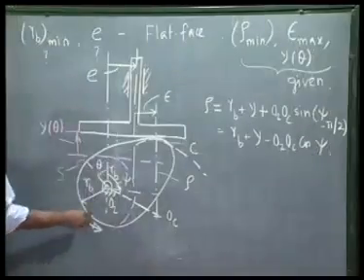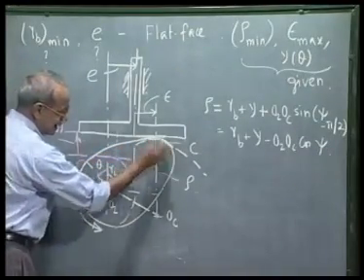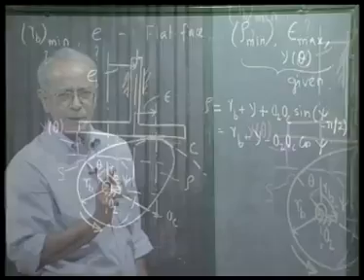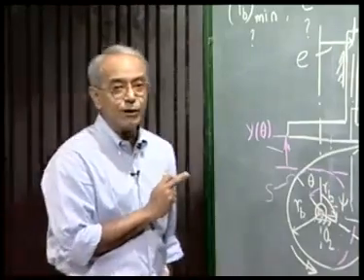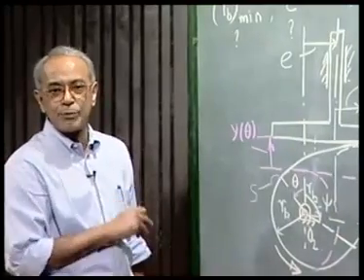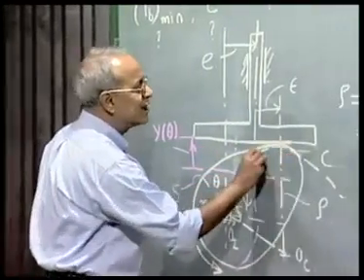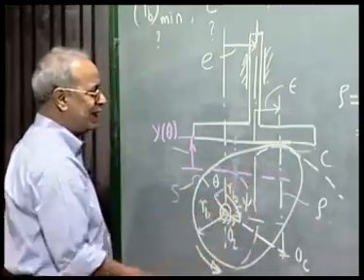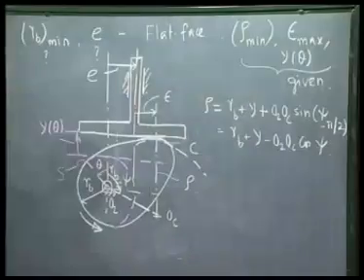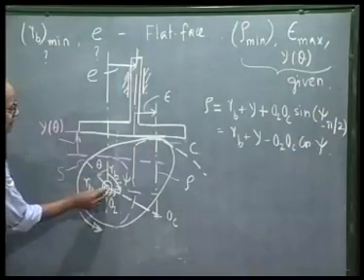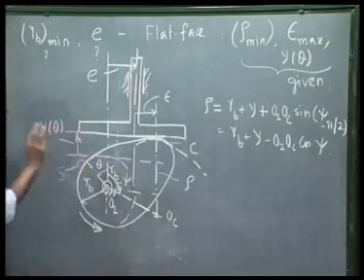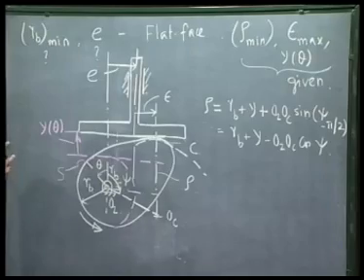Similarly, if I replace this cam by this circle, this equivalence is true only for 3 infinitesimally separated positions. That is very important, as we learned during the equivalent mechanisms for higher pair mechanisms by lower pair linkage. The radius of curvature is the same for this circle and this cam profile, so I can replace this cam by this circle up to 3 instants. And now we see O2, S and OC are not moving, at least for 3 infinitesimally separated instants.